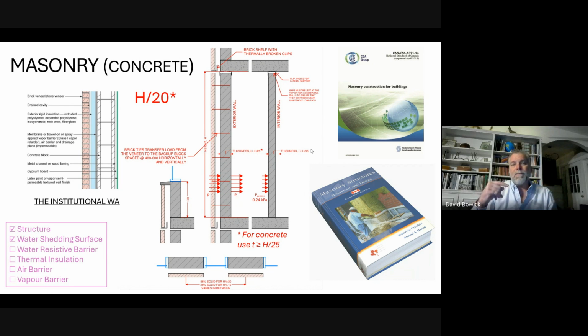So that same 3.6 meter tall wall can now be 100 millimeters thick, as long as it's a partition, and not a load-bearing wall and not an exterior wall. And once again, if you look at the top, we can see the little clip angles. So we don't want partitions becoming an unintended load path either.